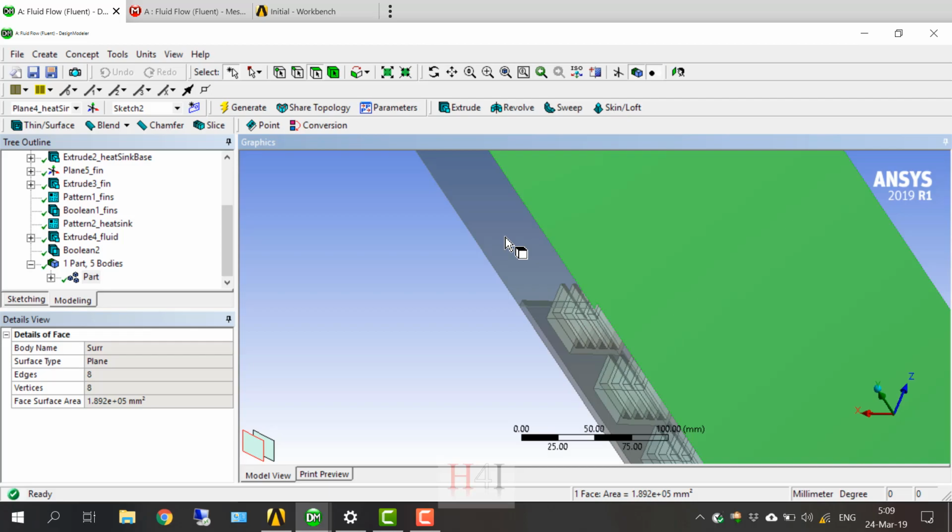You can find that at the solid surface the heat transfer is 10.9 watt, and on the fluid side you may find it 10.89 watt. There is a 1% error or more or less. Do you know what I mean? So this way I can create a mesh in the fluid domain which is very good and efficient with very small error.